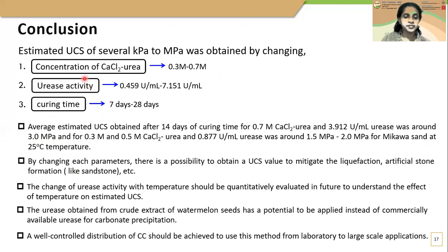By changing these parameters, there is a possibility to obtain a UCS value suitable to mitigate liquefaction and form artificial soft rock. And also the change of urease activity with temperature should be quantitatively evaluated in future to understand the effect of temperature on estimated UCS.